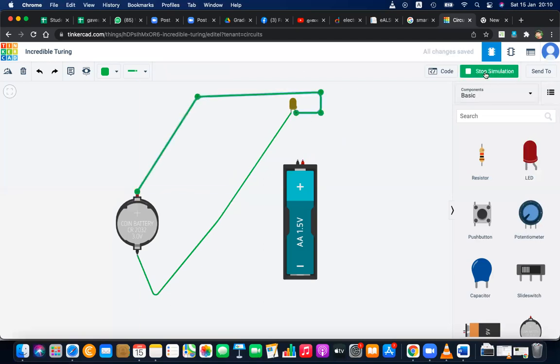Let's start the simulation, and you can see there's a problem. Can you read this and identify what the problem is? Yes, high voltage. Ampere, not just voltage, it is getting 61.9 milliampere, whereas the bulb needs only 20 milliampere. Right? You are getting more milliamperes.